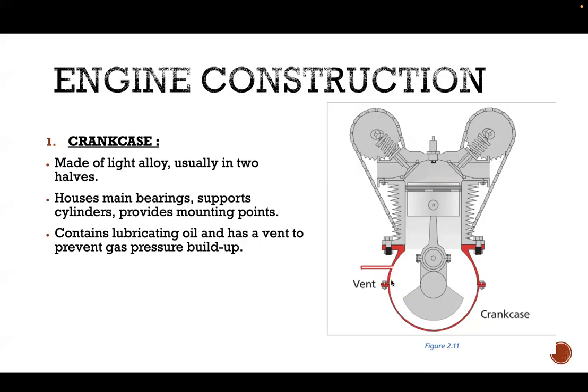Now, these things will have a vent in them. Why do we need a vent? Because whenever the whole thing is moving up and down, it is going to get hot, and there is going to be more pressure generated, because we also have an increase in temperature. So to reduce that pressure, and to cool your oil down also, we need vents. This vent is made in such a way that we don't have a leak of oil. It only allows the air to be vented out into the atmosphere and not your oil.